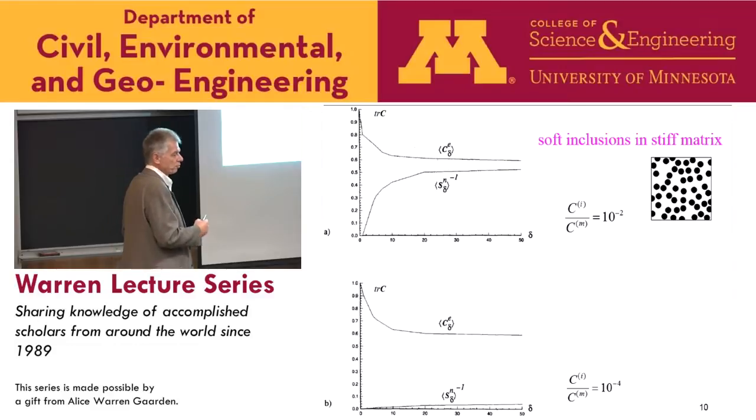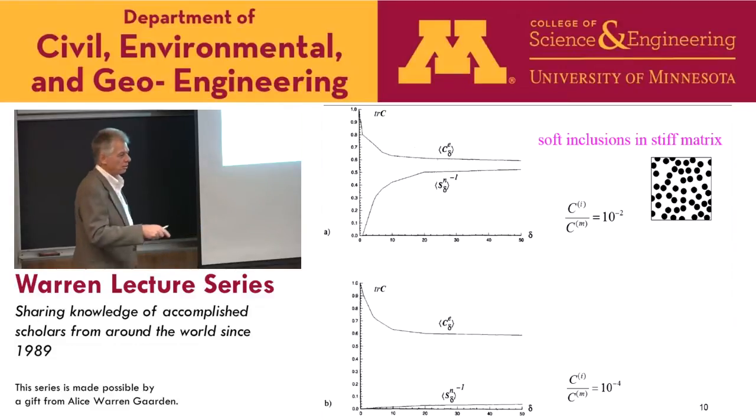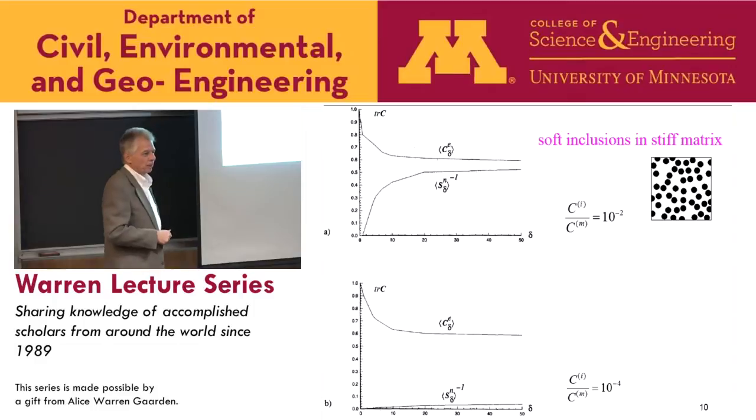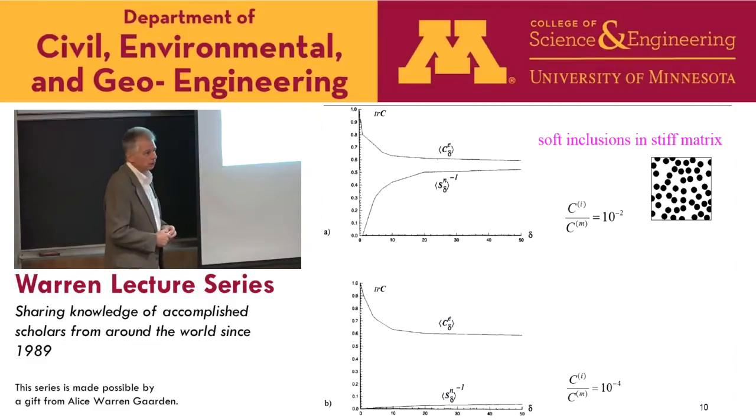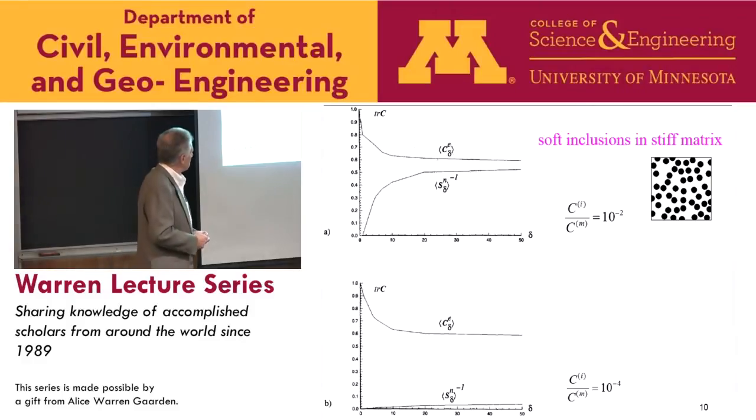It's a situation of Swiss cheese, how to homogenize a plate with holes, at which point the method breaks down, basically because the method doesn't work for phases which are not strongly locally elliptic. And one has to go to some effective medium theory, like Mark Kachanov is using Mori-Tanaka for those problems.